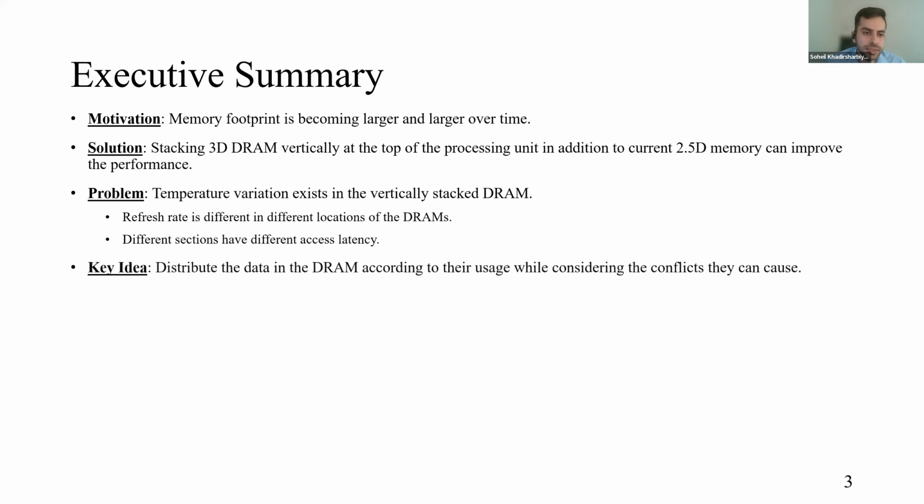So how we can use it is that we can place the most used data in the sections with the lower access latency. And at the same time, we want to minimize the number of conflicts caused by placing two hot segments in the same bank or channel.